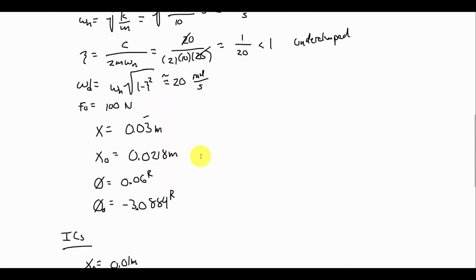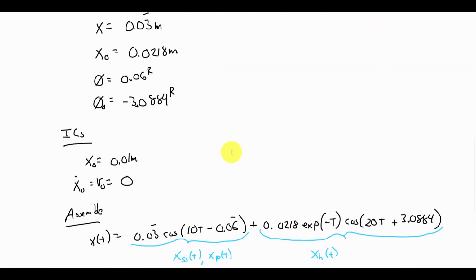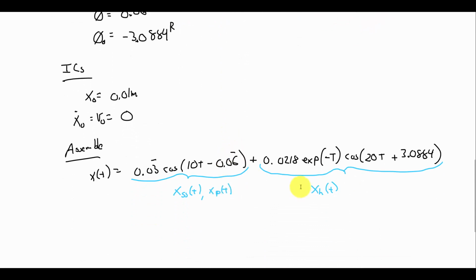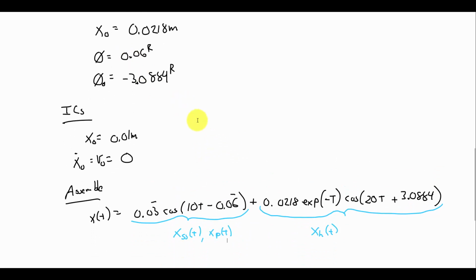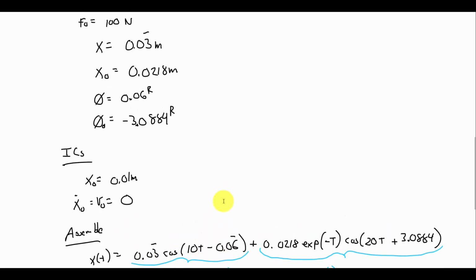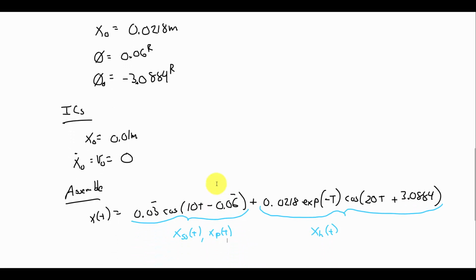So really what is going to change there, at least as the steady state response goes, is the particular solution. So how is the x and the phi, that's the only part that goes into the steady state solution. The x naught and the phi naught only are affecting the homogeneous part. But in the steady state, how is its amplitude going to change, x, and how is the phase going to change, phi, if we allow omega to vary.